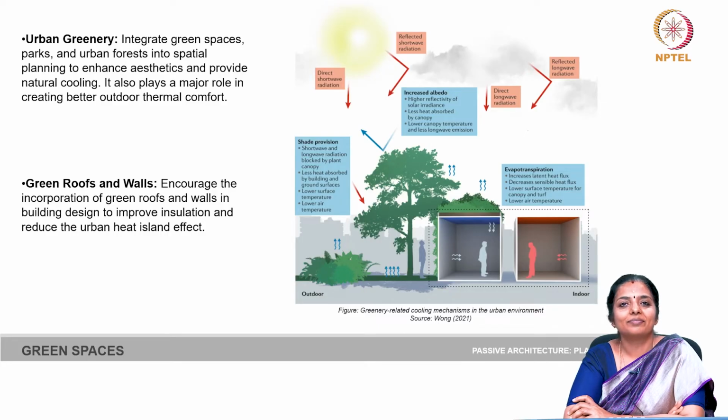Hello students. So last class we had seen how to have green practices at a planning level, at a building level, as well as at a small campus or settlement level, to ensure that we give appropriate openings, we place the buildings in such a way that we do not cause too many wind shadow regions, and we facilitate cross ventilation.